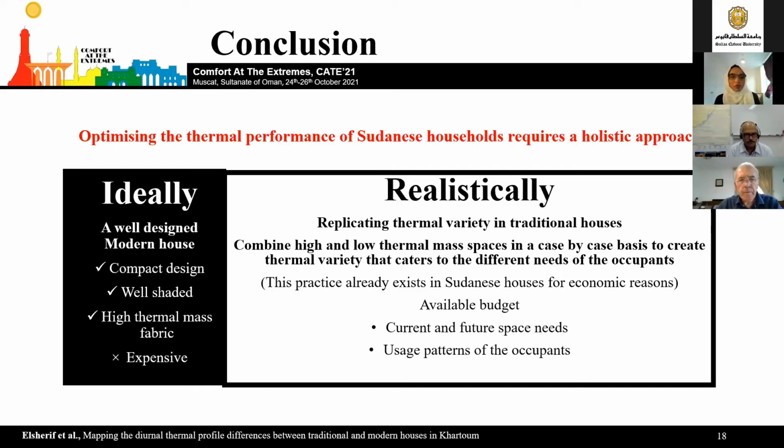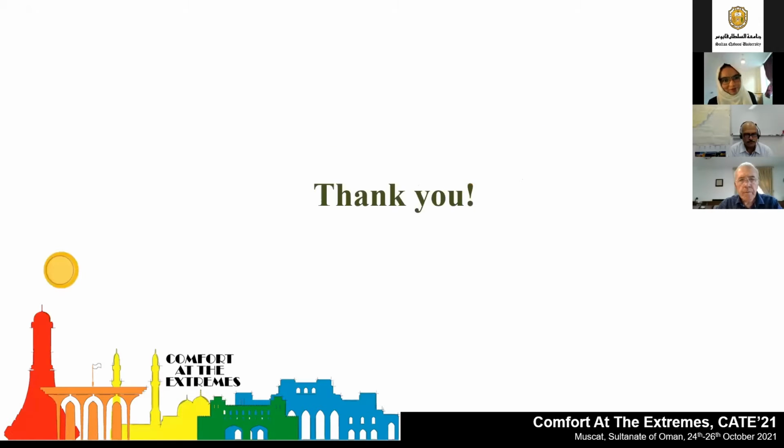The reason this solution is good is because the practice already exists in Sudan. People already have different materials in the house because they expanded over time using different materials based on what was available and what they could afford at the time. So this is regulating the practice that already exists and using it. For example, this high thermal mass space will be comfortable throughout the day. It's preferred for a user that stays here most of the day, while this space is low thermal mass, so it will be best for a user that only uses it at night. Thank you. That is my conclusion.